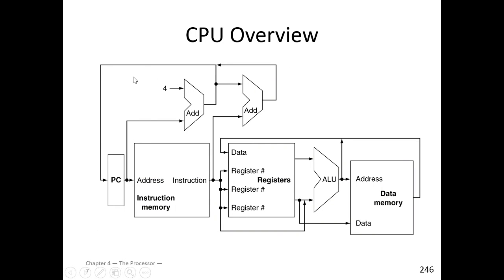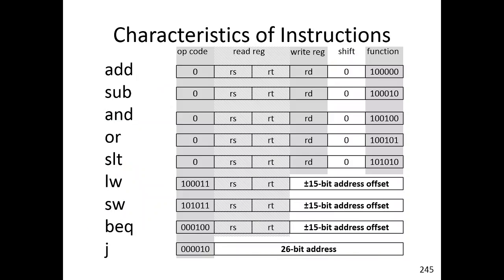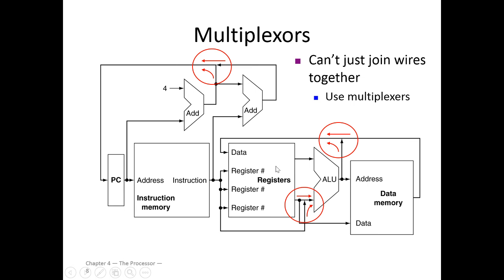Now this is where all that folds together, with some simple add. We start with a PC, so 32 bits here for PC, and then instruction memory, and then registers, and then the ALU, where the arithmetic operations are performed, and then data memory. We just follow this path. Different paths equate to different instructions, but this is not holistic or true. This is just a sample model, so don't get stuck on this.